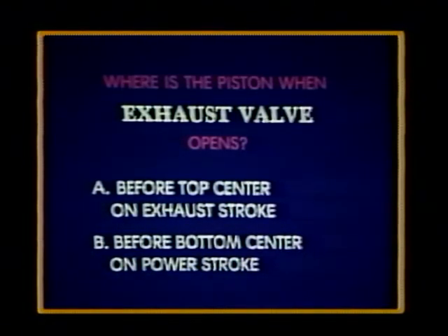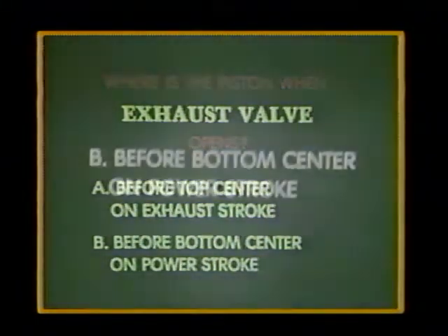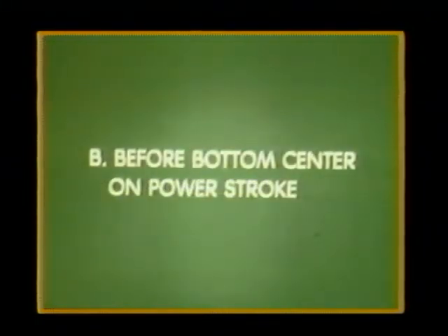Let's take a moment and review what we've learned with a couple of questions concerning power production. Question: where is the piston when the exhaust valve opens? Is it before top center on the exhaust stroke or before bottom center on the power stroke? The correct answer is before bottom center on the power stroke. The exhaust valve opens when there is still pressure from the expanding gases in the cylinder to start the exhaust gases flowing out.